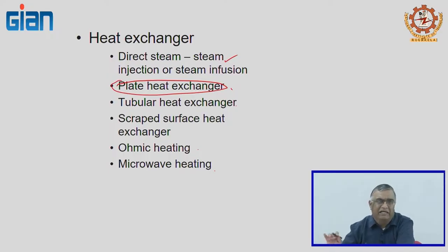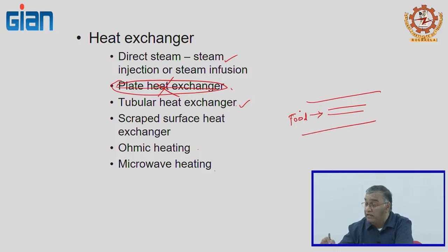In the case of aseptic processing, you may be using particles, like liquid and solid particles. So, normally we do not use this heat exchanger here. Typically, you may be using a tubular heat exchanger. So, basically you have a tube, the food product is going through it, and then you have what I call the heating medium going on the outside. So, this is your heating medium. Thereby, as the product moves through the heat exchanger, it is going to heat.